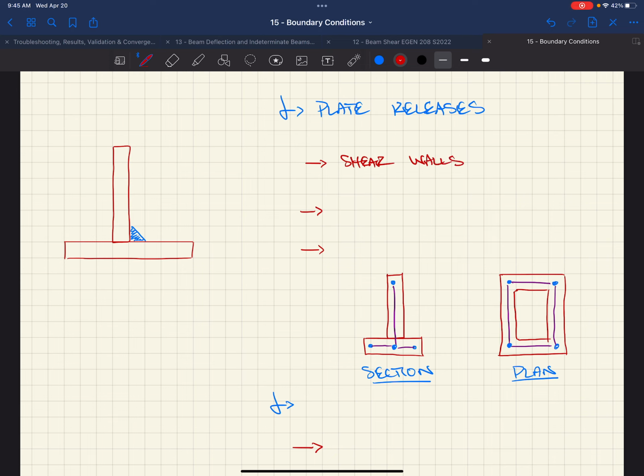Obviously, as we talked about, if you model something in 2D, say a multifamily or a hotel, and maybe you decide to put concrete shear walls on the end of it, not very common, but say you do. You probably won't design the entire building in one model. You'll look at all these flexible diaphragms, distribute all the loads to that big concrete wall, and put that wall in maybe fix the bottom, and you put all these loads at the different levels. In this case, you probably don't really care about releasing the out of plane direction.